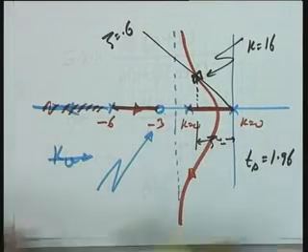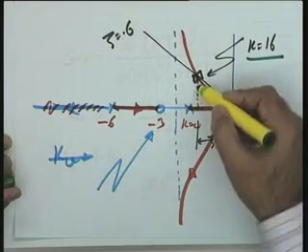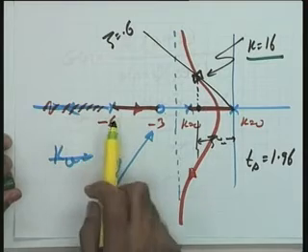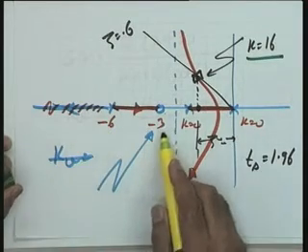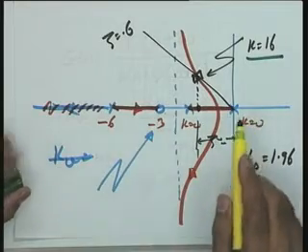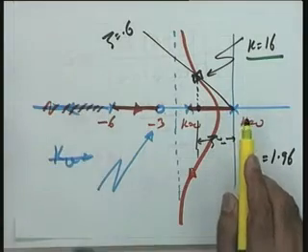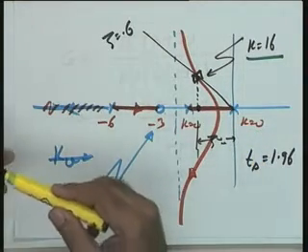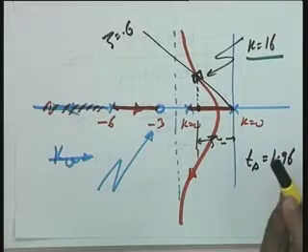Yes. The last point, k is equal to 60 in this particular case, and the value of this particular point can be calculated. Now you find the third pole lies in the region -6 to -3, and there is a great risk of the dominance condition being violated. You see this point was raised by one of you, that if the dominance condition is not satisfied, what to do. There is nothing we can do but trial and error, but if we remember some guidelines, the trial and error gets reduced.